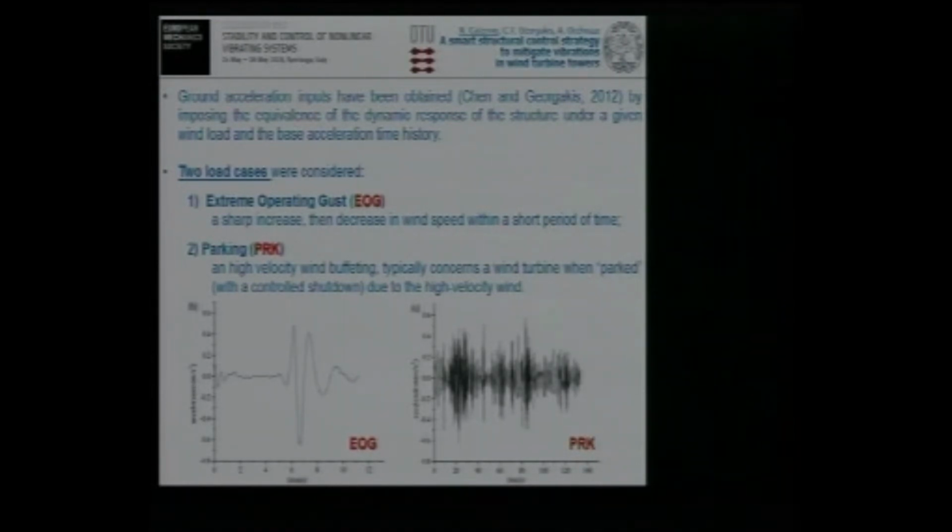These acceleration time histories have been imposed at the base and were derived by Professor Chen and Georgakis from DTU, using a software that they built. The software is able to convert the effect of wind loads into equivalent base acceleration time histories.